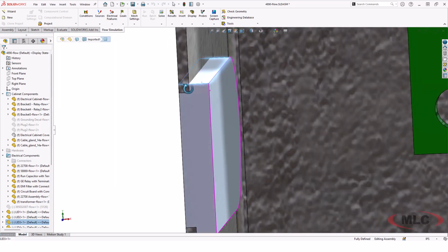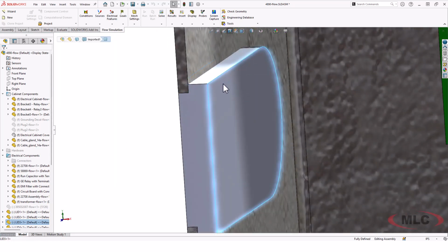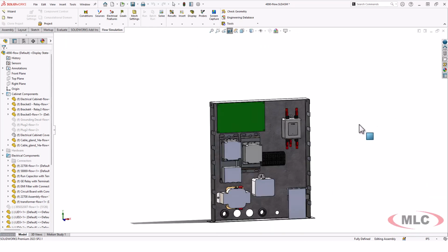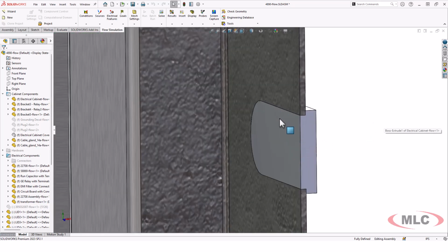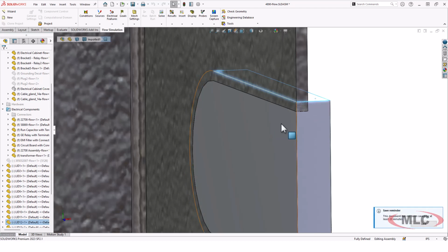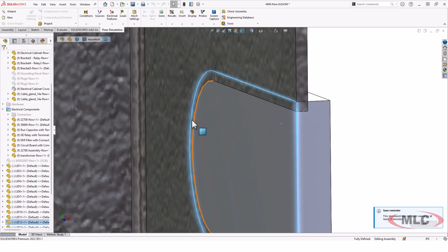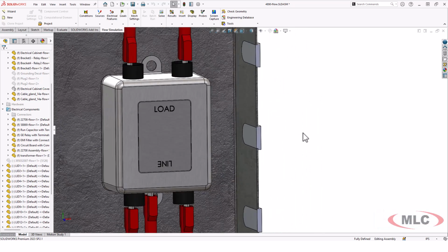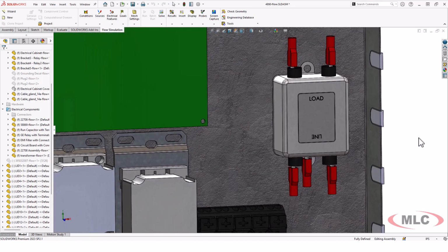And so now I have multiple faces that are going to be considered boundary conditions, whereas on the other side, I grabbed the inside face. And so now that's a lot simpler. If you ever see a face that's sort of halfway in, halfway out, don't worry. Anything on the outside is just going to get ignored. You're just worrying about what's on the inside that's touching the fluid, right? That's where those errors about not on the fluid solid boundary comes from.